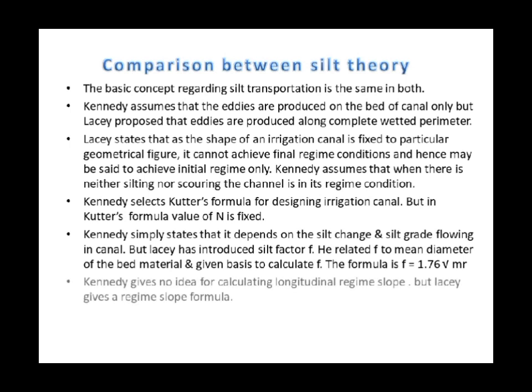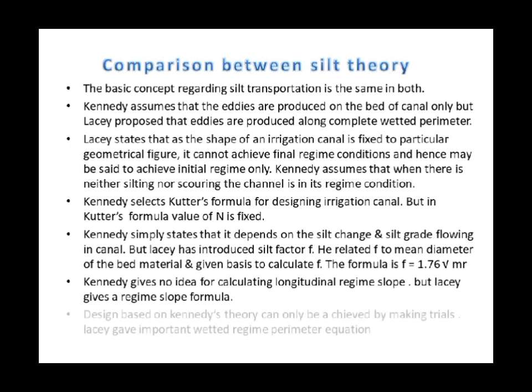Kennedy gives no idea for calculating the longitudinal regime slope, but Lacey gives a regime slope formula. Design based on Kennedy's theory can only be achieved by making trials.